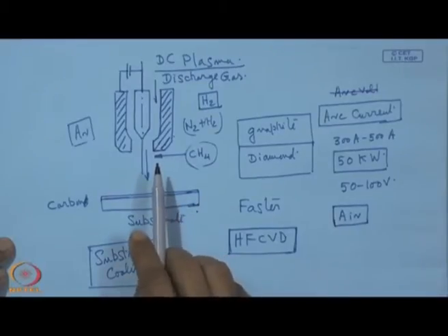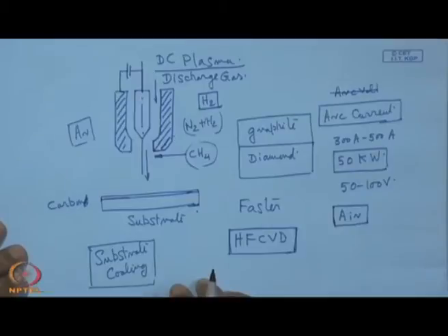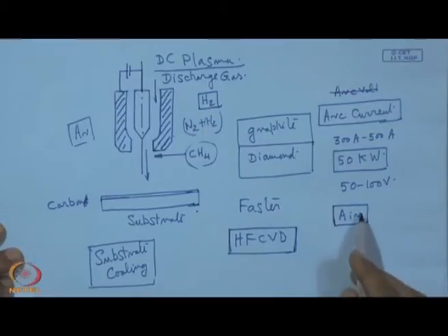Then abrasive size, the material which is being deposited here, that size is also one parameter. Normally say a grain size of 50 micron or 100 micron is a size which can be used, but if we have a lower size, then handling this by air in that powder feeder becomes a little complicated task because of the absorption of moisture in the system.